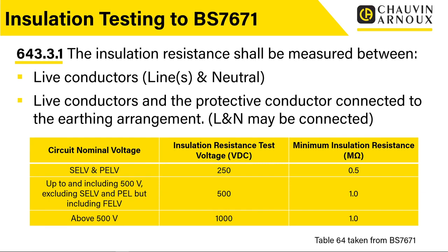Now there's very little within the electrical wiring regs that would have a voltage above 500 volts. Some circuits relating to neon lighting may fall into this category. Some considerations of PV systems potentially could get into this sort of voltage range, and they are considered separately.